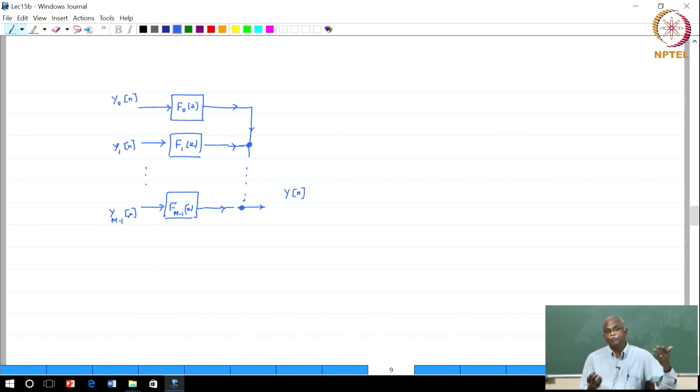In the input case, it seemed obvious that there would be a need for filtering. Where this filtering would come into play is in the following scenario. Let us say y0(n) was y0'(n) upsampled by a factor of M, producing y0(n). This means that y0(n) has multiple copies of the spectrum, and you don't want all of them, you want only one particular copy. So, this F0 would be a band pass filter which takes out the appropriate copy.